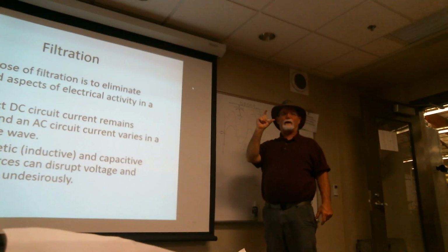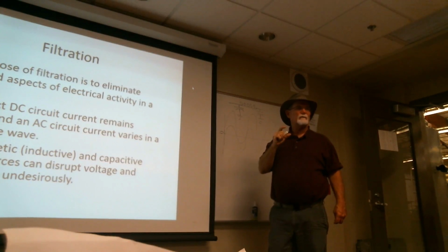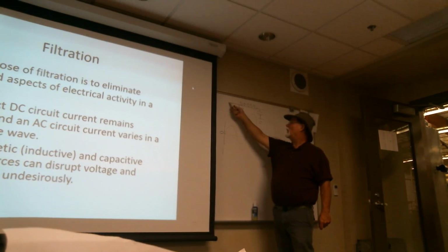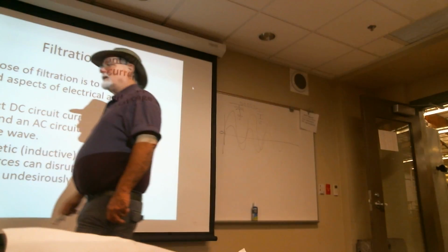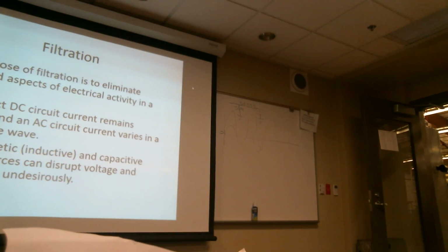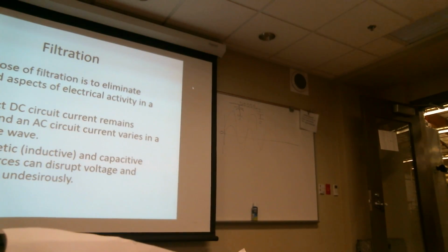In fact, you buy those little Radio Shack, well, there is no more Radio Shack, but you buy one of those little Radio Shack alternator noise biscuits. They've got 3 wires, 1, 2, and 3. Okay, that's all they've done, and they've tuned the inductor and capacitor to take out frequencies that are common to alternators.